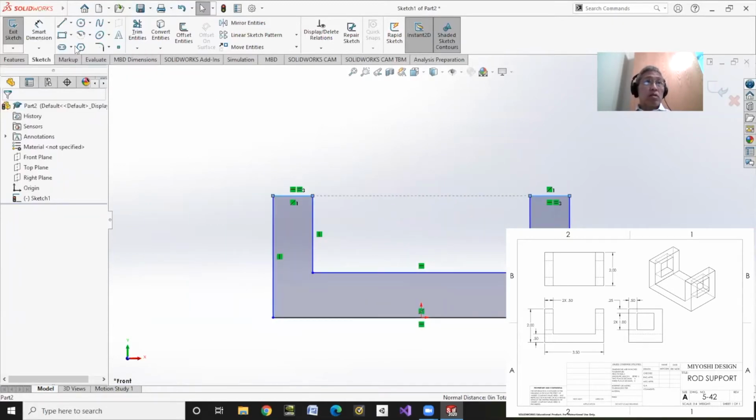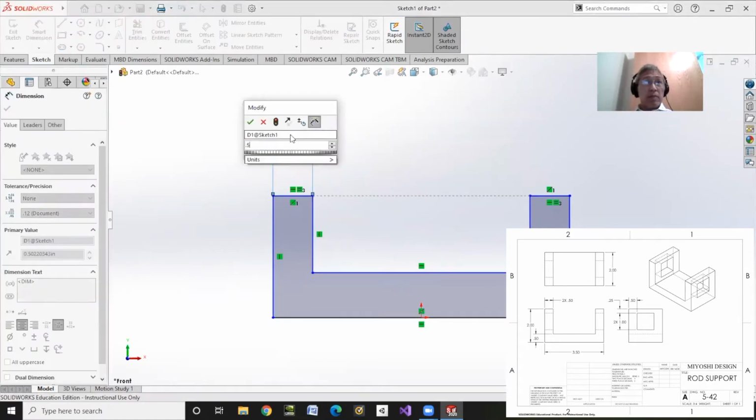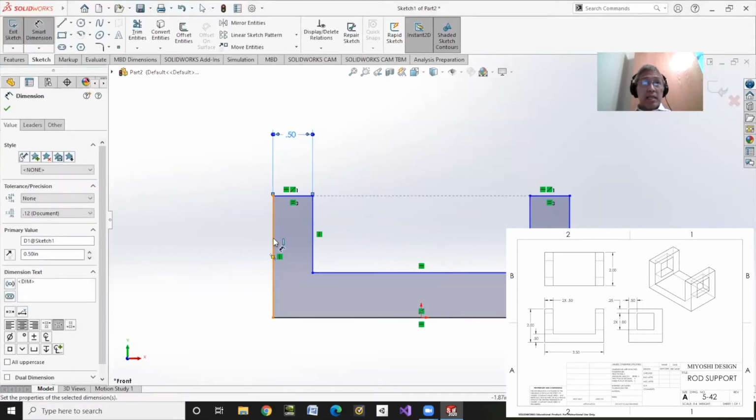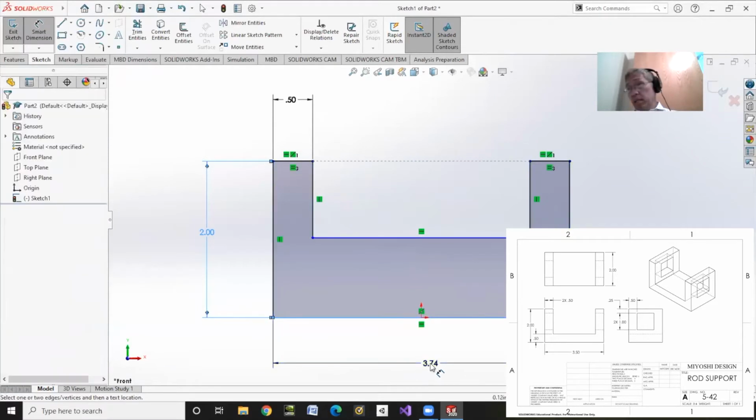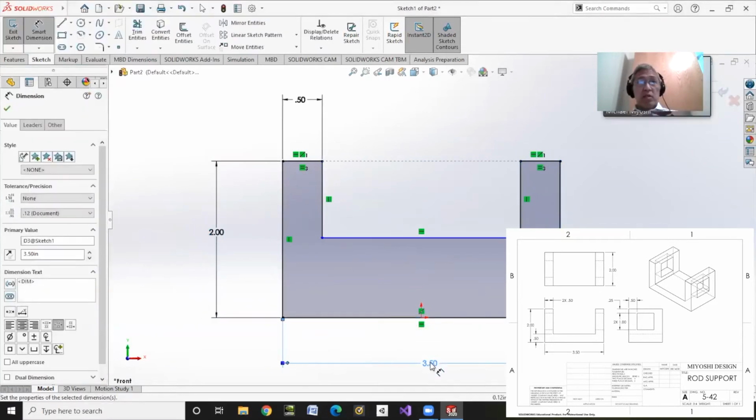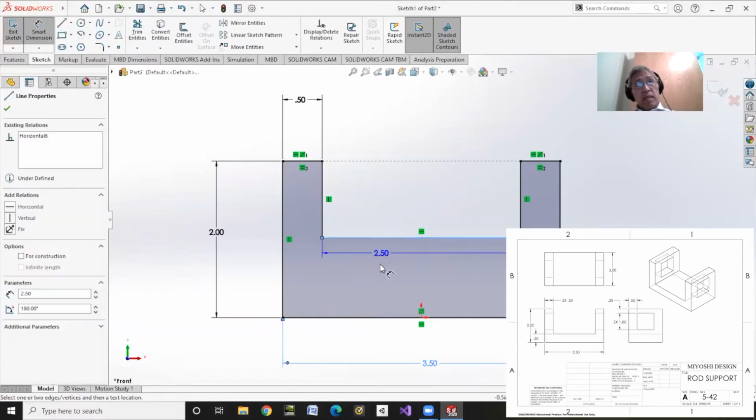All right, so smart dimension this guy. It says in my book that this guy is 1/2 inch edge. And so look, it's pretty close, but I'll make it exact, 1/2 inch edge. The height here is 2, and the length here is 3.5. So I'll just put 3.5 instead of doing 3 space 1/2. And then the thickness of this guy, so I'll grab the line here and the line here. The thickness of that is 1/2.